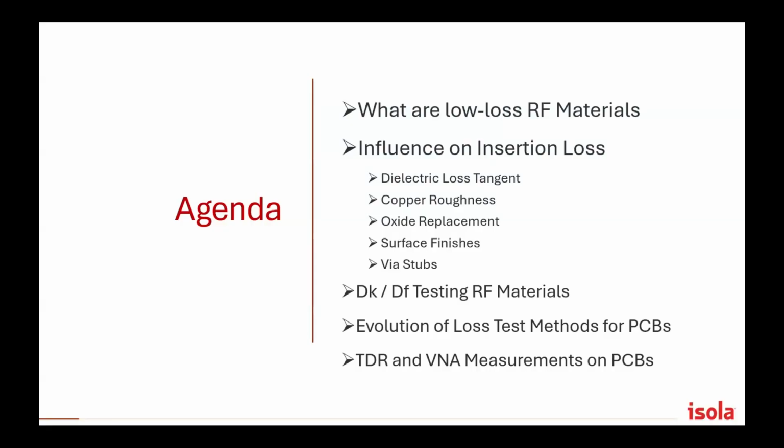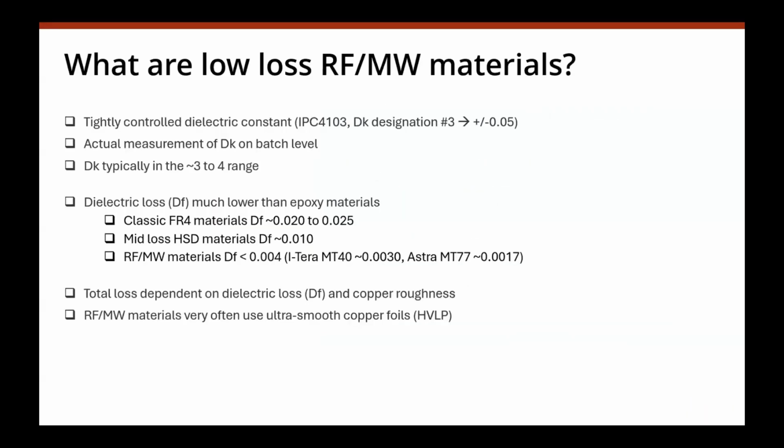Dk/Df testing of materials. Whenever you want to run a simulation up front, you need some data, and that's better based on testing. When you have the testing of the insertion loss on a PCB, because no matter how good simulation really gets, it's always based on assumptions, and you only know for sure once you have done some actual testing. And then I'm going to shine a small light on what else you can do with TDR, VNA. So that's what we want to talk about.